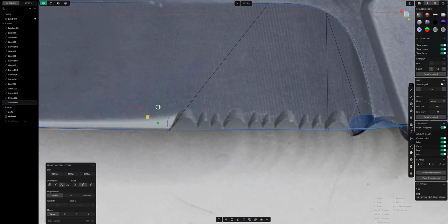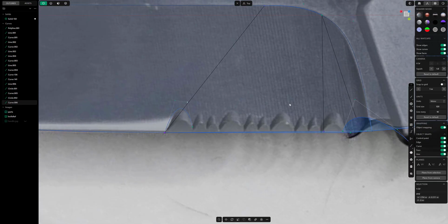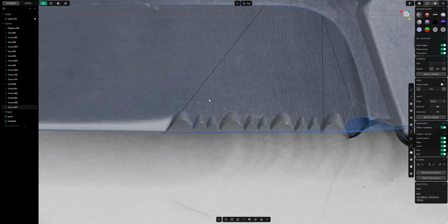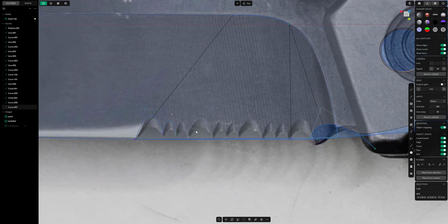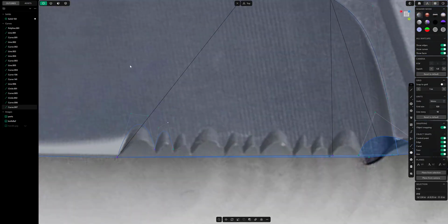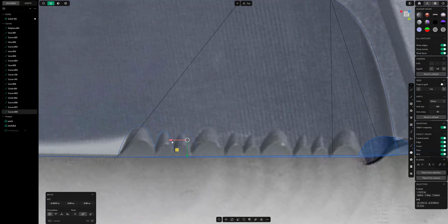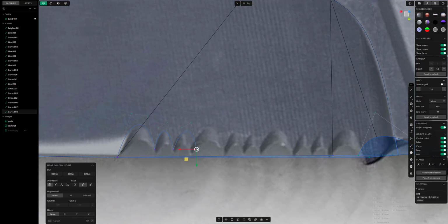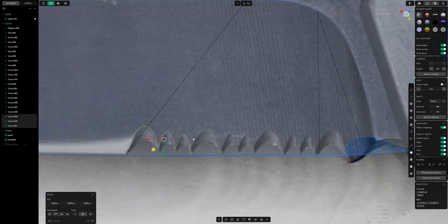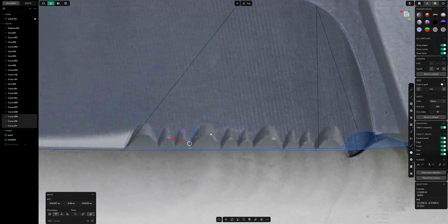The serration on the blade takes a little bit more effort. So just do a 3-point curve. Have a couple of control points at the top, and then I'm just going to line these up and create the pattern. So this is 1 large followed by 2 small. Once I get 1, I can go ahead and duplicate that, and if I need to do any adjustments, I can go ahead and adjust these. Once I have the pattern, duplicate and just move it into position.